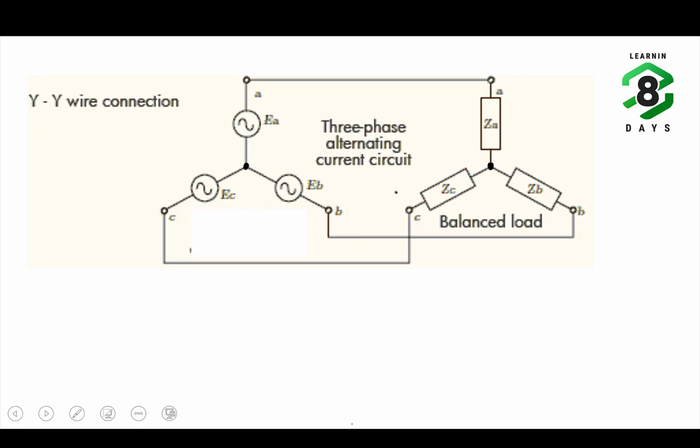Either it is a source neutral or load neutral or the neutral of any star connected transformer when a power system is operating under balanced condition. That is, when a balanced three-phase source is supplying energy to the balanced three-phase load, all the neutral points are at a zero potential. What is the potential of the ground?